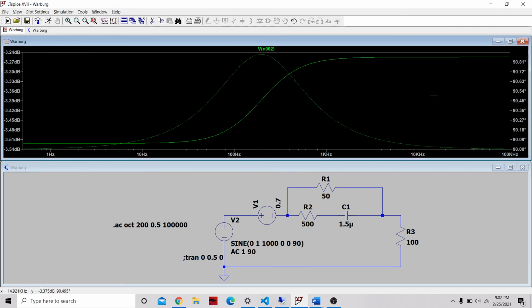And we see that this is acting as much more of a bandpass-like effect, which may be desirable on your electrode, probably is not this narrow of a bandpass frequency. So we know that electrodes with these properties might not be particularly good at recording bioelectric events, depending upon what bioelectric event you're looking at. If you're trying to record from neurons, this would not be great. Might be okay if you're looking at something like an EEG.